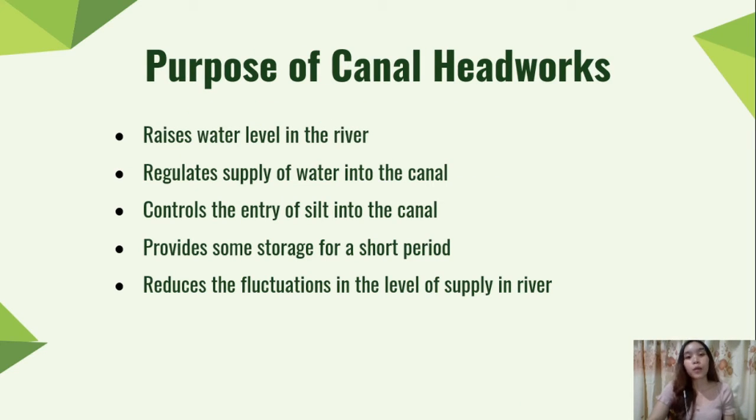Next is the purpose of canal headworks. The first is that it raises water level in the river. Next, it regulates supply of water into the canal. The third, it controls the entry of silt into the canal. Fourth, it provides some storage for a short period. The fifth one is it reduces the fluctuations in the level of supply in a river.